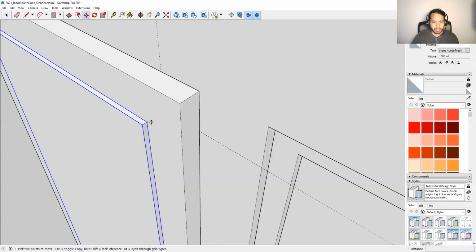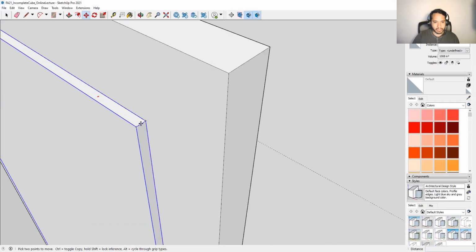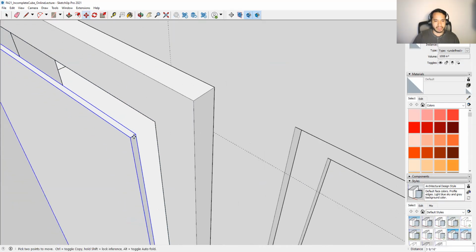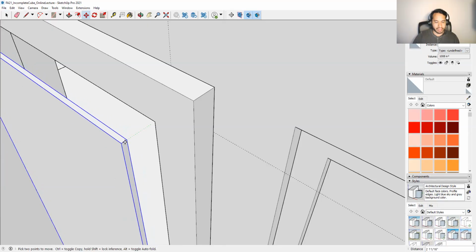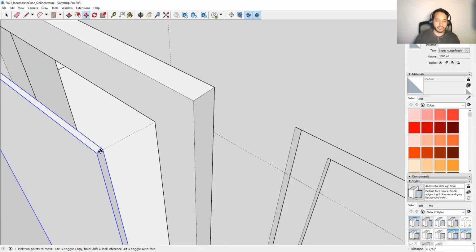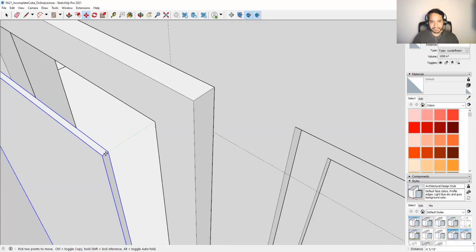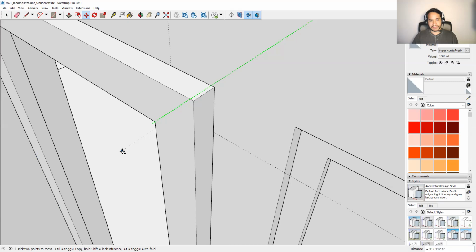The way we do that, we'll use the move tool. We grab the glass at the center, on the edge here. We pull out so that we know which axes we're on. Sometimes if I'm on the other side of the building, I'll be on the red axis. This side, I'm on the green axis. So that's why I pull it out a little bit first so that I can see which arrow to push. So I'll hit the left arrow key.